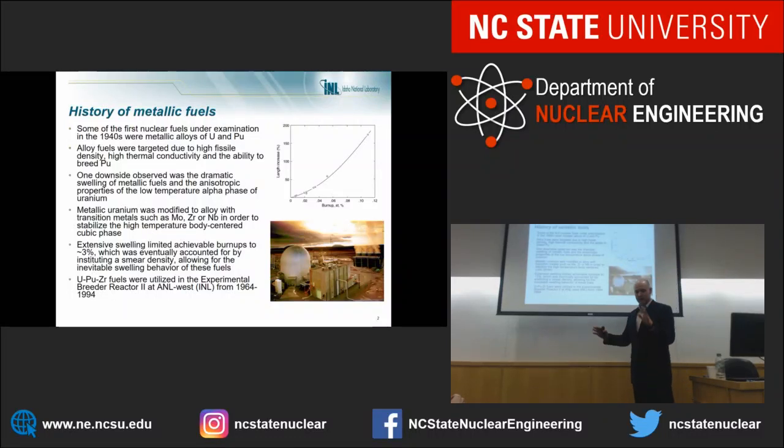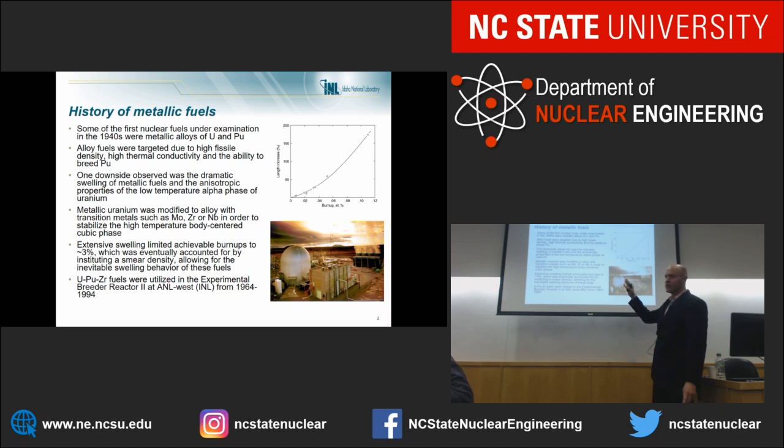So, the history of metallic fuel is very old, started from whenever the first reactors were done, so back in the 40s. They were of primary interest because of the ability to pack a lot of uranium into the fuel alloys. They're also a metal, so they have much higher thermal conductivity than uranium dioxide.